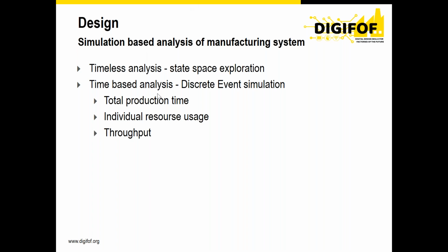Through simulation, we can do two things. We can do a timeless analysis, so only in principle an exploration of the state space of our design solution. And this can give us information about the connectivity, about the possibilities or impossibilities. So it can say if some states are reachable, are not reachable, if forbidden states are reached, and things like that. But more important, and you will see from the operation, is for us to do a time-based analysis, usually based on discrete event simulation, because this gives us on one side information of what really happens,